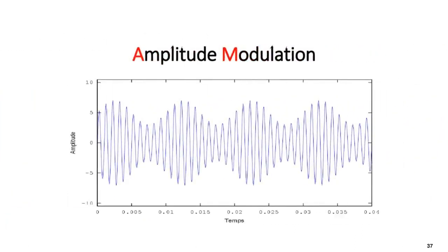And we have various techniques. So here is amplitude or AM radio modulation. Our audio signal modulates the amplitude of the carrier frequency. And then when our radio receives this signal, it strips out the carrier frequency, and we're left with our audio. Now, being amplitude modulated, this can be impacted by overhead power lines. That's why when you're driving in your car with an AM radio on, you get under power lines, all you hear is 60 hertz hum and buzz and noise, because the radiation of the power lines is an amplitude modulation.